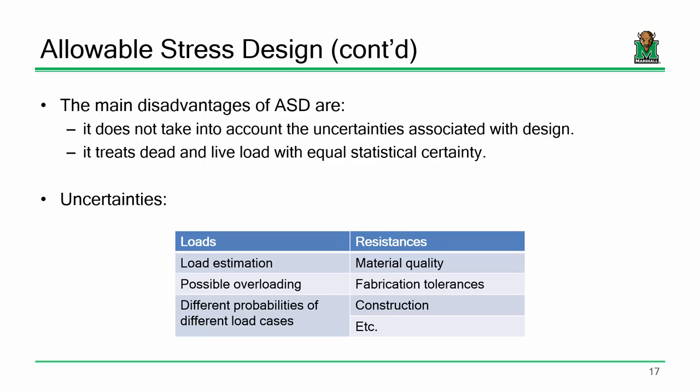What I mean by problems with that is that there's a fair amount of uncertainty associated with what we do in design, and just using a factor of safety doesn't incorporate that. Let's go back to my example. How much do we say that this table would fail at? 800 pounds? Now, let's think about this realistically. I take this table. I load it until failure, 800 pounds. What about this table? Isn't this the exact same table? Should it fail at 800 pounds? It should. Is it going to fail at exactly 800.0 pounds? No, there's going to be a little bit of scatter, right?